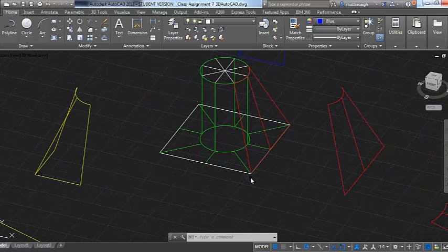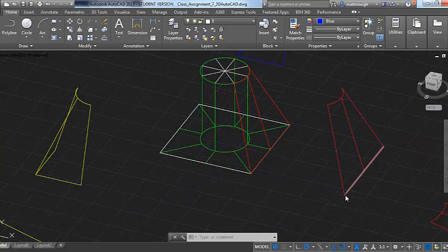This just comes from a little bit of experience, and there are a few little things that come up when you do that. You'll notice I'm press braking to a single point here and then up to round. What I would do is, from the center point of that pattern down to this corner, press brake half of this pattern down to this one corner, and from center over to here, I would press brake down to this corner.